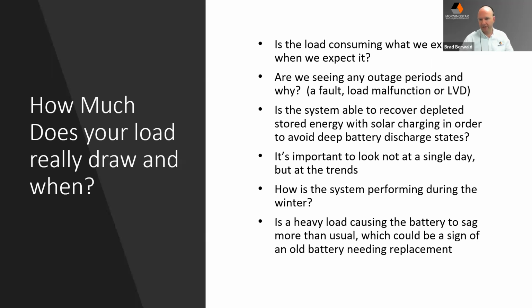So when you're looking at those loads, these are additional questions to ask: is the load consuming what you designed for or what you expected? And when you inspect it, is it running more frequently than you realized? Depending on what's happening at the site, are we seeing any outage periods? Are there any periods when the load is actually off? That could be indicated by a fault, a load shutdown because of a short circuit, possibly damage to the load, or a low battery. We do disconnect the loads during deep discharge of the battery.